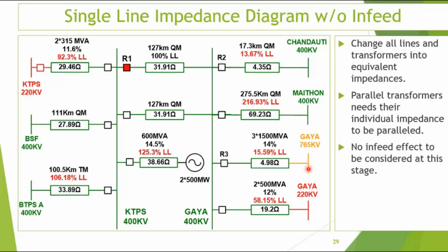I have a fault at the lower voltage level, my relay operates from the higher voltage level or a different voltage level, which should not be the case. This fault should be cleared by its own voltage level first. This relay should never operate for this other voltage level fault. Same for this. And this is a very short line, that is our problem. The zone 2 of this line will encroach into the zone 2 of this line, as will be seen just a little bit later.